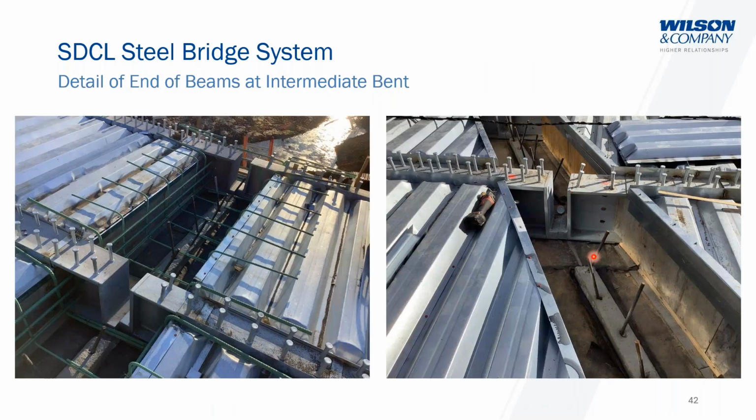As you can see here, this is your typical detail. You saw the one on the right before. Brian had shared that. That was the one with the skew. You can see those girders were pretty well the same width and height throughout there. You can see how the contractor laid these dowels in an X pattern. And what I believe the contractor did was, once they laid the steel on the left, which are these upside down hat bars, if you will, they would then insert their steel plate, which then also went through the girders themselves, right?